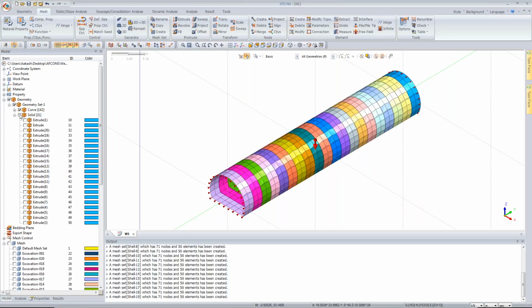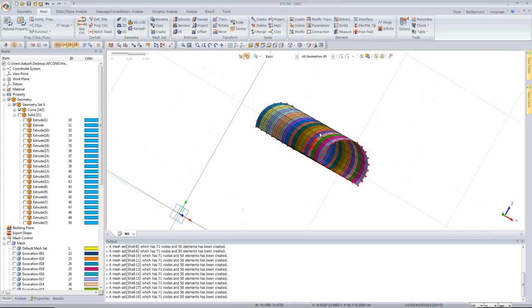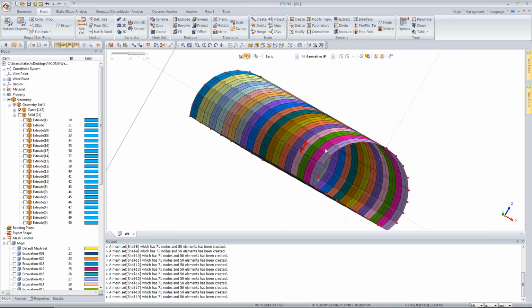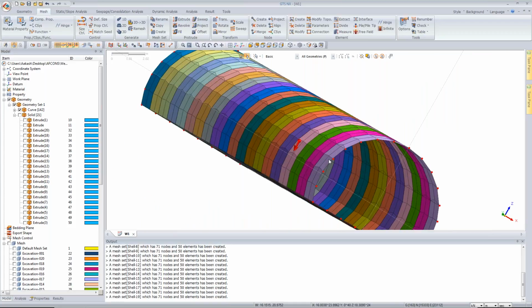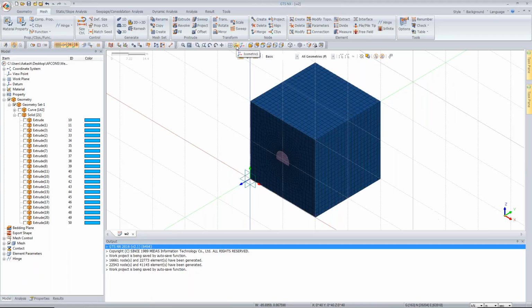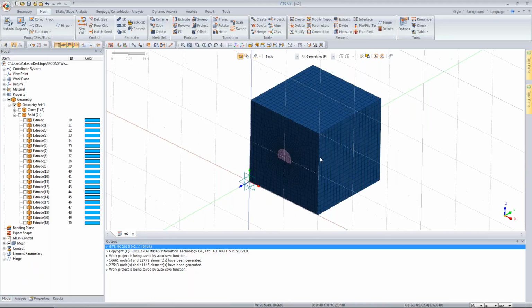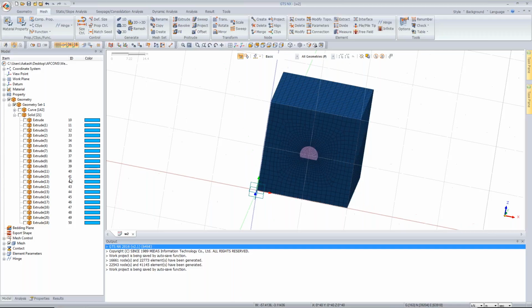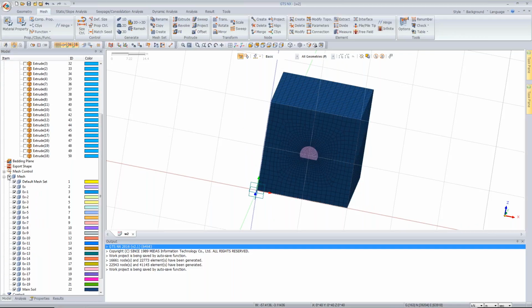If you hide it, the program has extracted the mesh set. With the hybrid element, what you get is more like a rectangular element. So if you want to align the coordinate system of the shell plate elements in one direction, it's easier to do. Fine. So this is how basically you can take care of it. This is already meshed for us, so I will repeat this step again so that it becomes more clear.